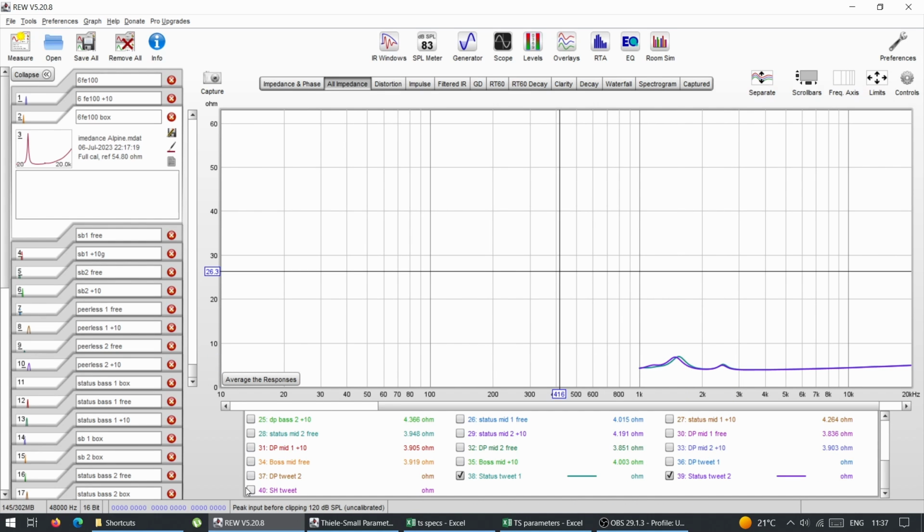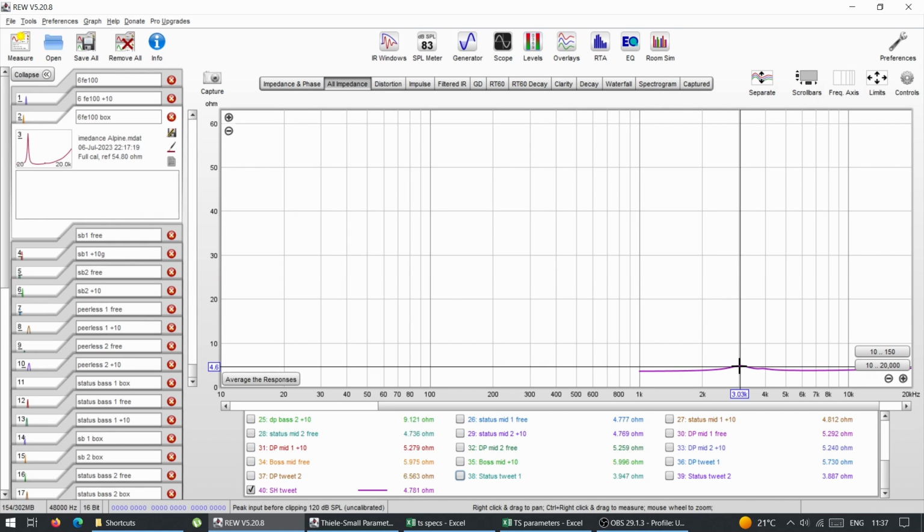And I have this SH, the shitty tweeter that I have, and the shitty tweeter has an FS of 3K. If you remember, this is from a coax set of Kicker KS. It has some passive crossovers applied, and yeah, 3K FS, so it cannot play low at all.